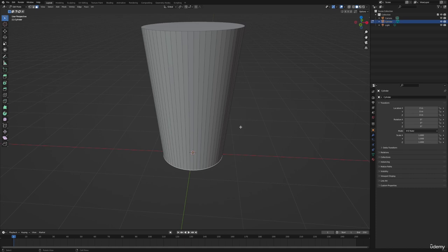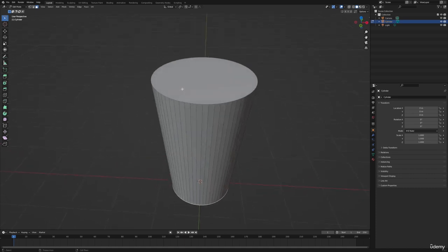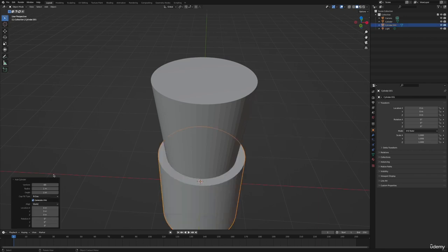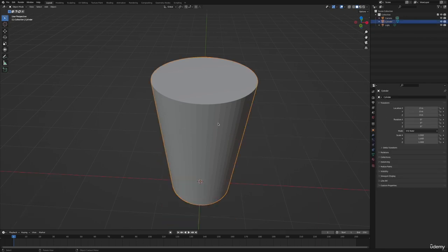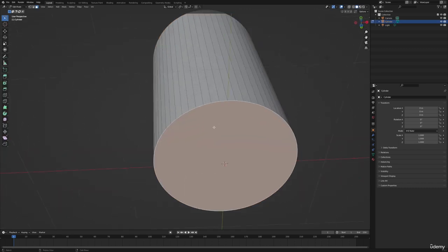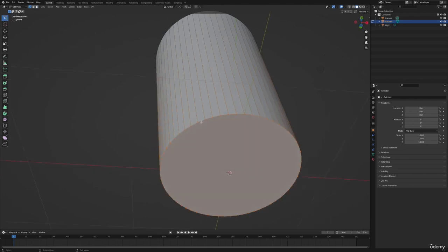One thing we haven't done yet, though, is the creation of points, edges, or faces. So far, we only have the points, edges, and faces that were created for us. If we press Shift A in object mode and add a cylinder with the vertices set to 64, we have now worked with these points. We've moved those points, and at the end of the day, scaling a face is just moving all the points in a coordinated manner. You can see that if we select a face and then go into vertex select mode, we can see that we've selected all the points that define the face.